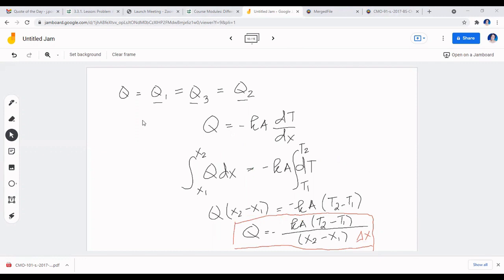Okay, so as I have written on the screen shown to you a while ago, your Q, the amount of heat transferred, should be equal through all plates, whether we're talking about the stainless steel plates that sandwich the copper plate, represented here as Q3. If we go back to the original DE, the original Fourier's law written in mathematical form, we separate variables: we cross multiply the differential of x here, keep the k A and the differential of T on the other side, then place in the appropriate limits of integration.